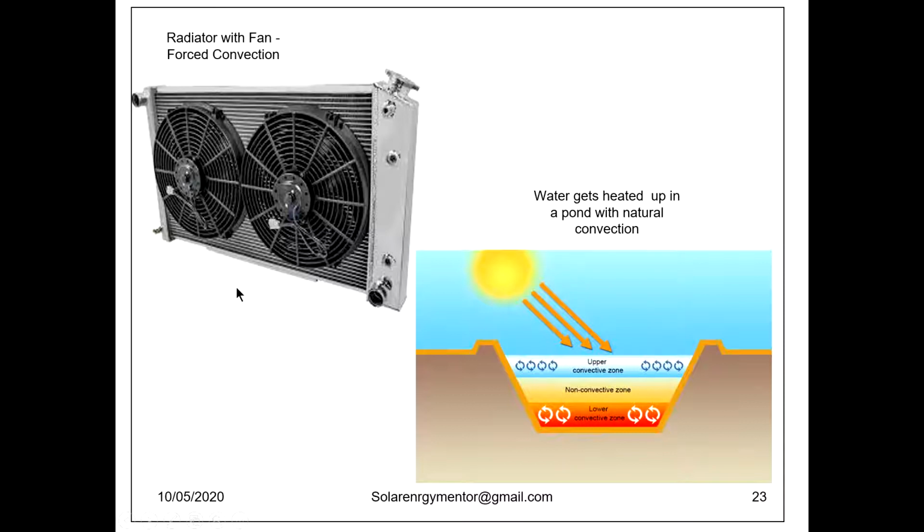This is a radiator type of heat exchanger. Some hot or cold fluid is entering, for example cold water at 1 or 2 degrees Celsius entering into this radiator. These are the radiator fins, and the fans force air over the surface of these fins, so the air becomes cool. In all the air handling units in air conditioners, these types of radiators are used where cool air is needed. So here air is forced over the fins of the radiator, and this becomes a case of forced convection heat transfer.